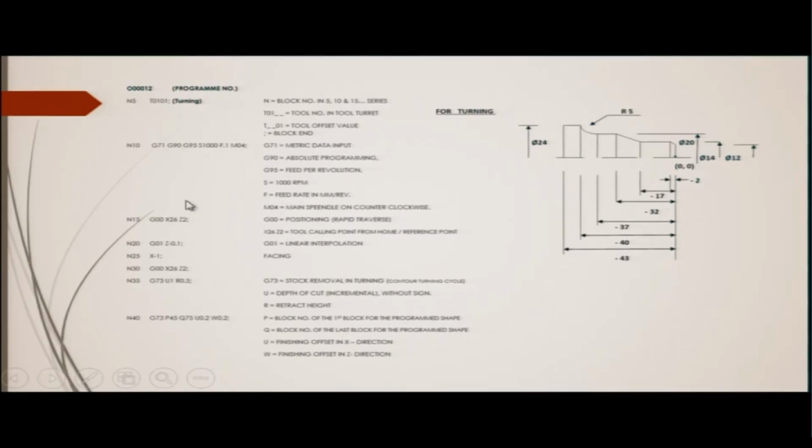G is the G code, there is a series of G codes, and that series will be from G00 to G100. So, 101 different G codes are there, and each code means something. I will show you that table where these G codes are tabulated, and you do not have to remember all of these, that is not possible. You will always have a handbook while making the program for a particular part for the CNC machine. So, that table can be readily used, and you can see that if you need, for example, some system that is to be used for data input.